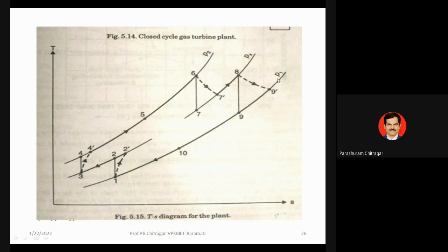Let us say P1 is the atmospheric pressure, because we said we are taking the air from the atmosphere. So this is atmospheric pressure. तो फिर हम लोग ने आइसेंट्रोपिक कंप्रेशन करते हैं तो इंटरमीडिएट प्रेशर पे लेके जाते हैं, let us call it Px, intermediate pressure. तो इसको कैलकुलेट करना पड़ता है, so it is simply under root of P1 and P2. अभी फिलहाल बता रहा हूं मैं आपको. तो ये Px इंटरमीडिएट प्रेशर तक हम लोग ने पहला कंप्रेसर में करते हैं.